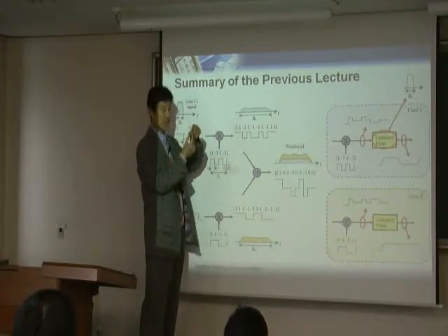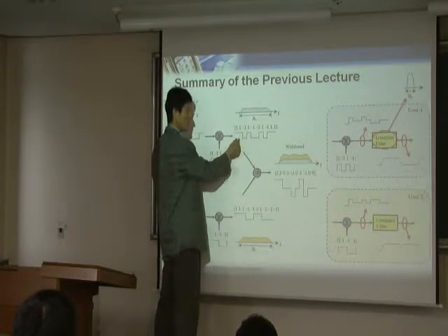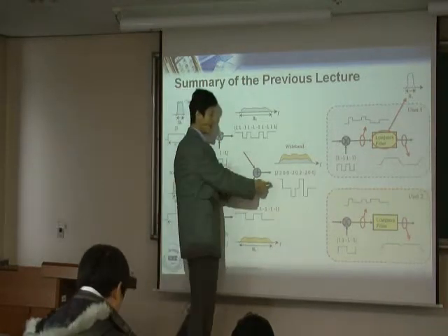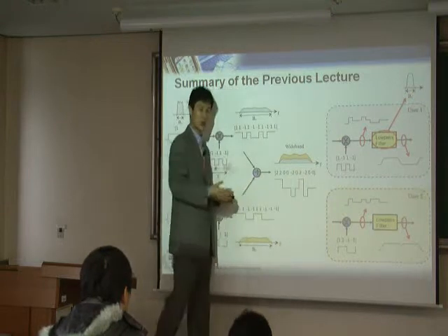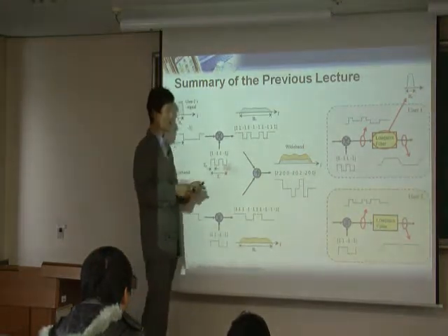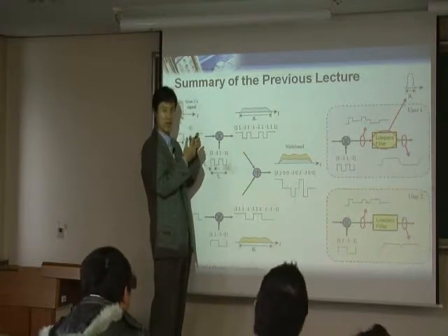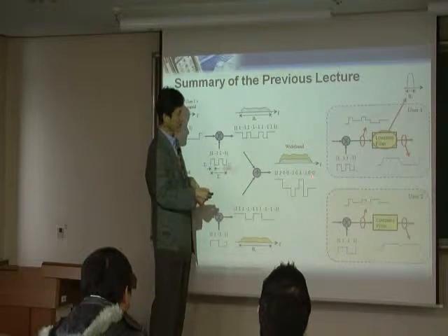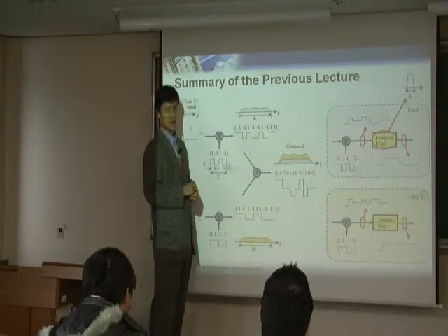Let's say that offset is a little bit big. If the offset is very small compared to your chip, then you are going to do a sampling anyway at some point, so that may not cause a problem. However, if the offset is a little bit bigger than that, still less than one chip, then your orthogonality is likely not 100% guaranteed.